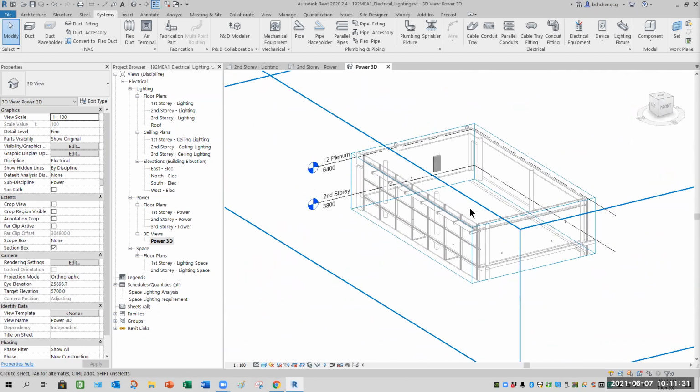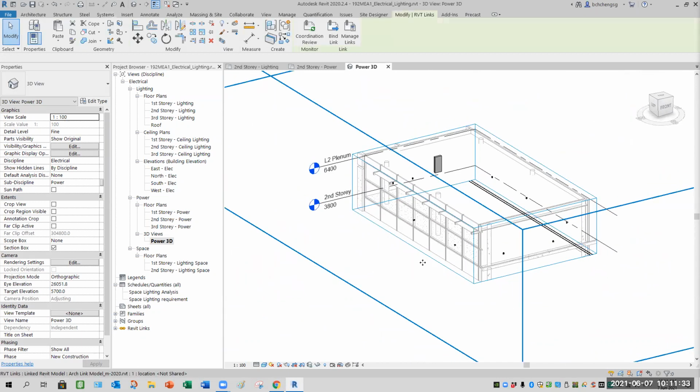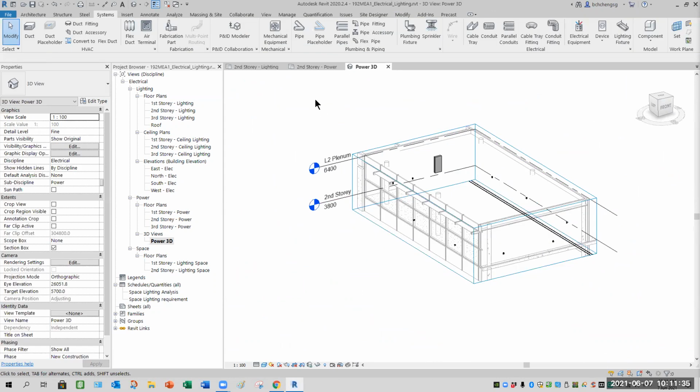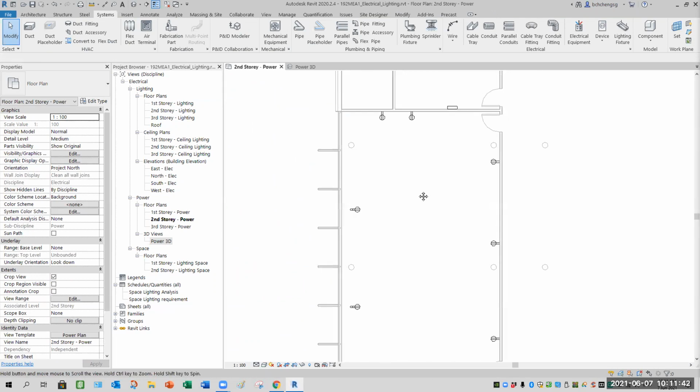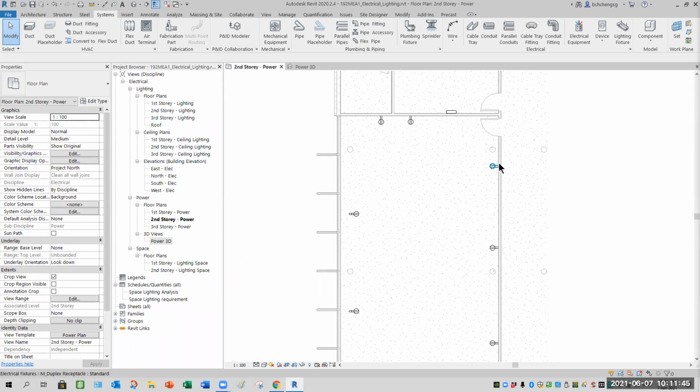Okay. So not only that, now if I go to my power plan here, is the distance mounting important? Or don't say distance mounting, you need to indicate what the length, the distance is, so that when they add a board or create partitions, they know where to lay the wire, with sufficient length for the socket.